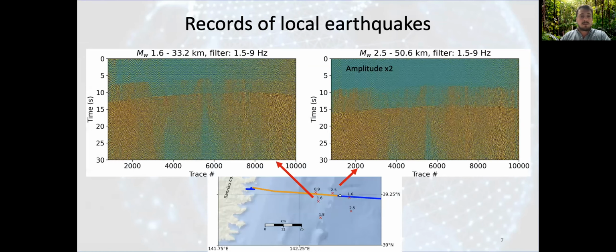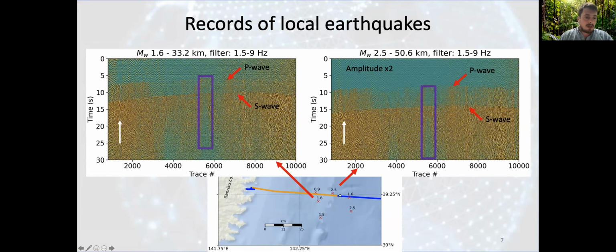So here are earthquakes. We use 6 earthquakes and we compute the autocorrelation and we stack the autocorrelations for the 6 earthquakes in order to have our autocorrelation signal. And in these earthquakes, we have both clear P and S waves. We have these inverted V shapes that are generally interpreted as a broken structure or fault structure, a complicated structure, let's say. And also we have these ghost regions where we have no wave signal, which can be due to a strong topographic change, for example.